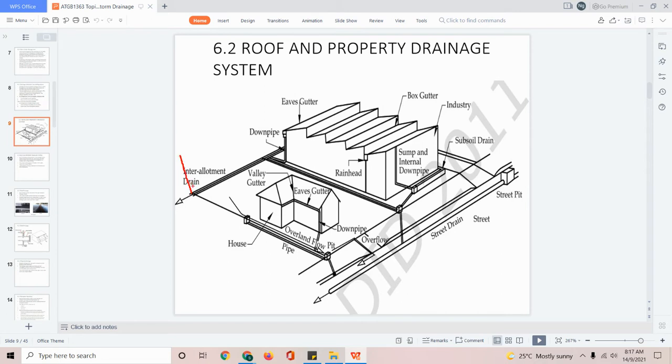When we have a reduction of this catchment area, then when the rain happens, the water will not be able to go back into the soil, so it has to flow into the drain. But if the drain does not have a high enough discharge rate, meaning it is unable to remove all the water in time, then it will start to overflow. So this is where flooding comes up.